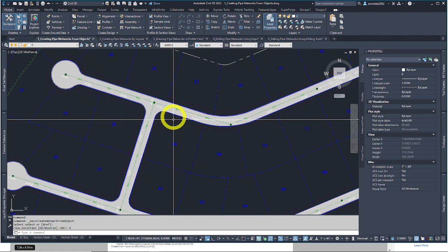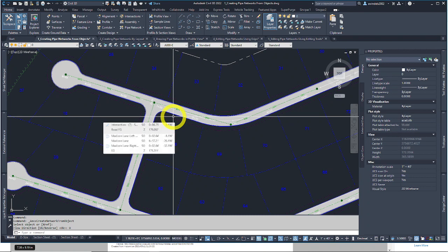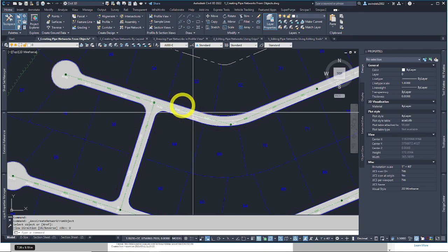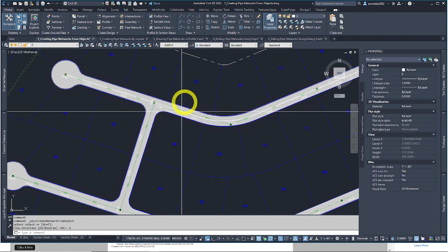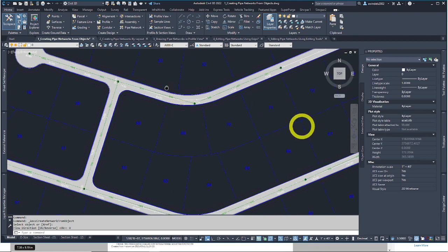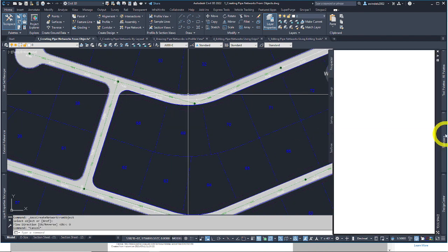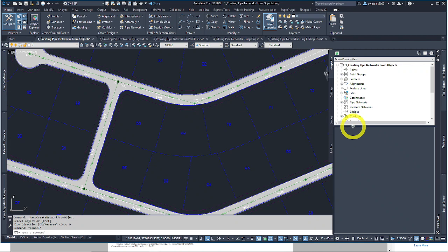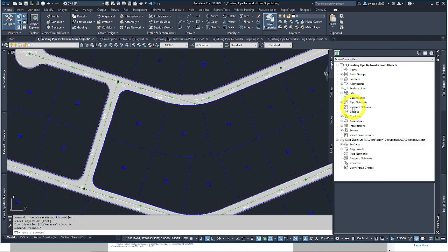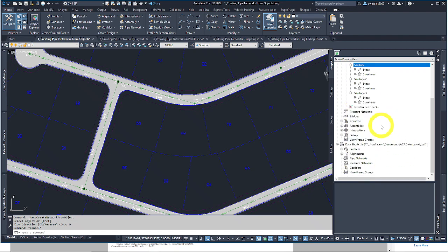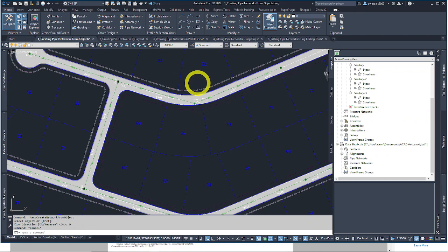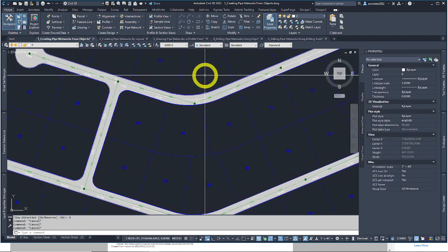So we made by object. We've converted everything that was our initial polyline into sanitary sewer pipes and structures, and now we have 3 pipe networks populated in Toolspace Prospector. Lower this. 3 networks we made here of various pipes and structures within them. So this is where they reside in Toolspace. Also clickable graphically, as we'll learn here shortly.